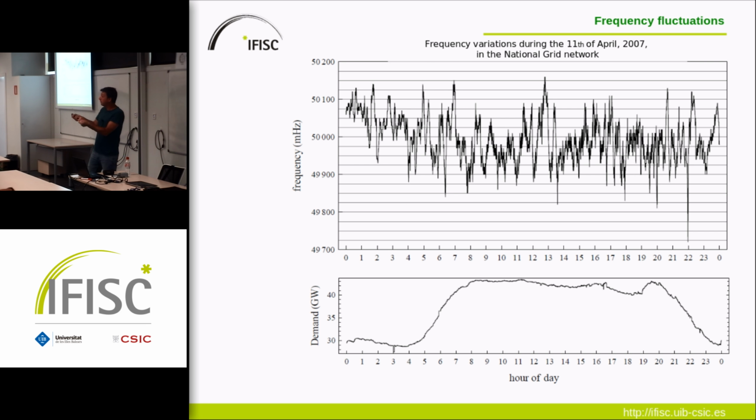Because we are switching on devices, you are braking, and then the power plant accelerates, and then you switch off and it accelerates too much. And this is fluctuating all the time. The system operator has the legal obligation to keep this within a range, which is actually 50.2, 49.8. This fluctuation is already out of what they are by law forced to keep in control.